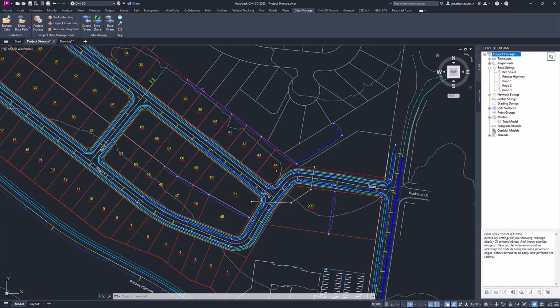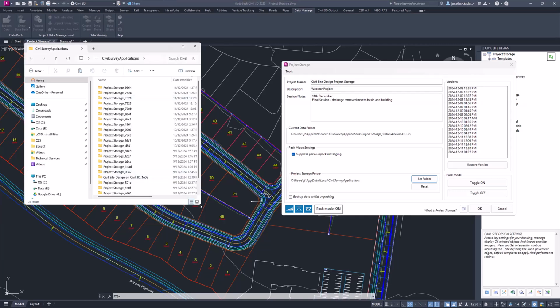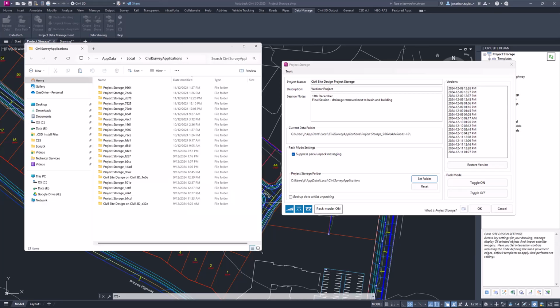The other thing, maybe just to make note of, because this is something that I tended to do when I used this software when I was on the other side of the fence, I tended to XREF quite a few things into my drawing. If you actually are exporting data to the data folder, like, yes, this maybe is a good point, plot file type stuff, then you probably should, as best practice, move it out of the data folder because when you reference it back in, two things are going to happen.